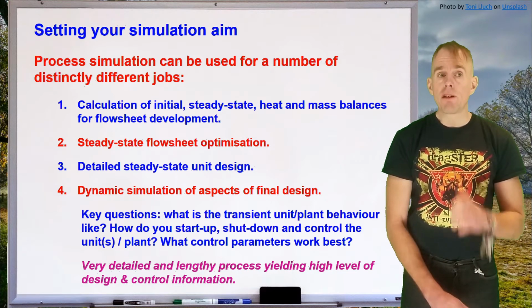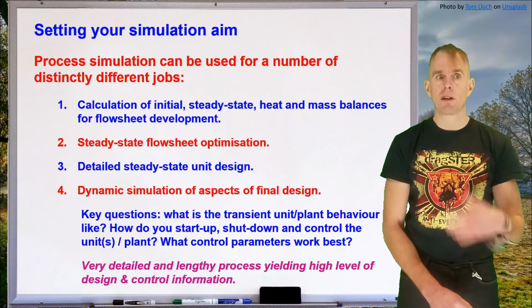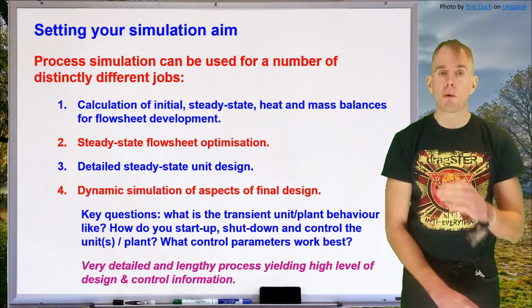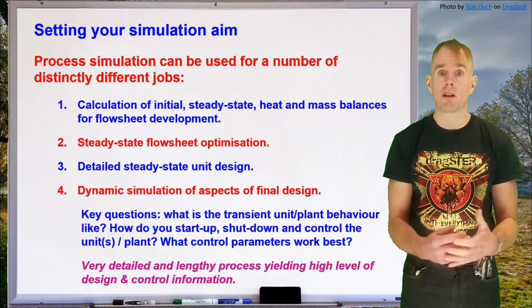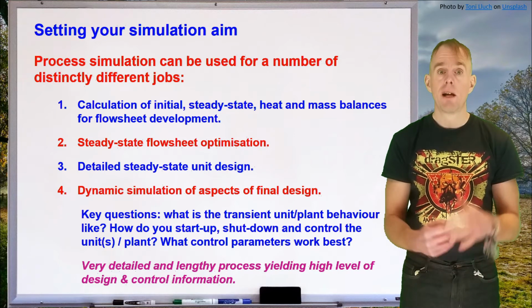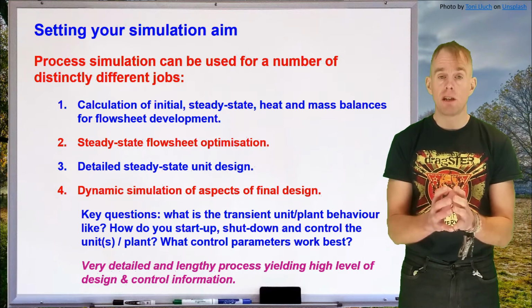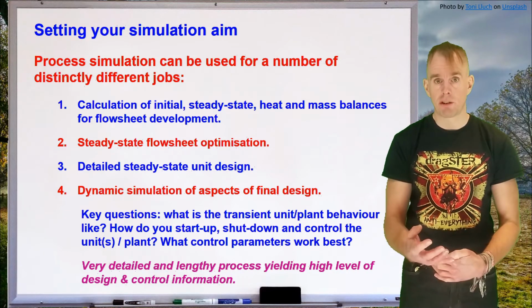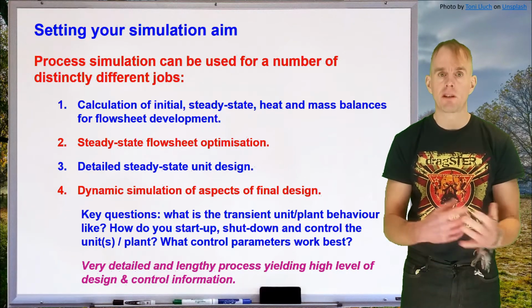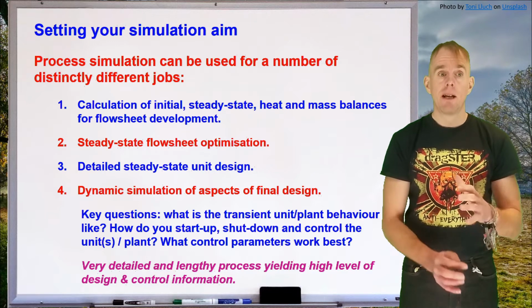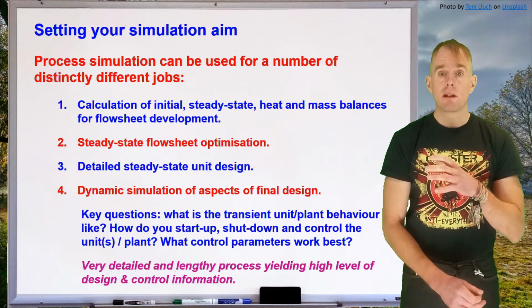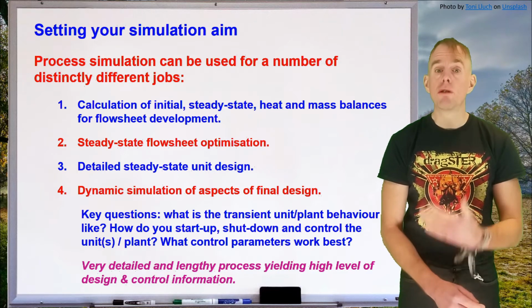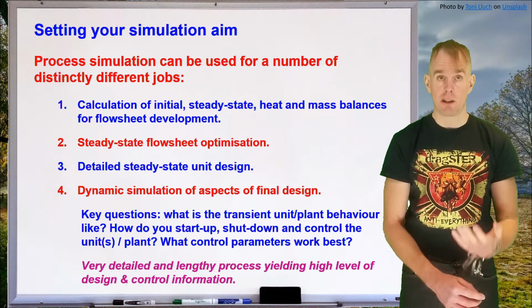In order to do this step of the design, yes, you need to have done the first three stages of the design, but also you need to have progressed the unit design to completeness as well. Because now really you're assuming that the unit is going to be as configured, and you're looking at the control systems and the instrumentation systems and the dynamics associated with them. So dynamic simulation can take an order of magnitude longer to do than steady state simulation, just as a warning.